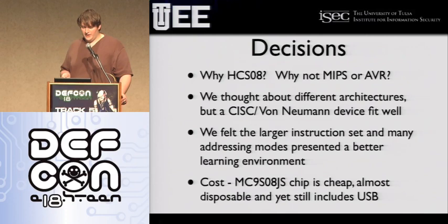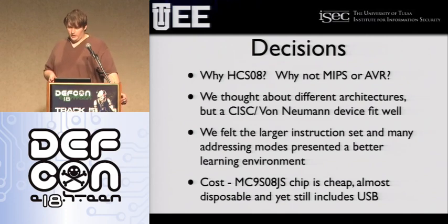When we were doing this, we had to make a lot of decisions about what to use, and a lot of the textbooks for computer organization use MIPS, and we kind of abandoned that and went with what we knew, and what we knew would be more difficult to teach, but would give people a better understanding of assembly language. The instruction set for HCS08, which is the processor on the development board we built, is a little more complicated than something like MIPS assembler, but it's more similar to x86 or something.